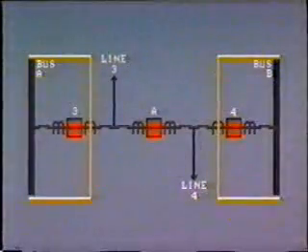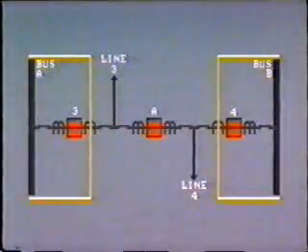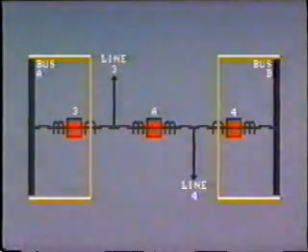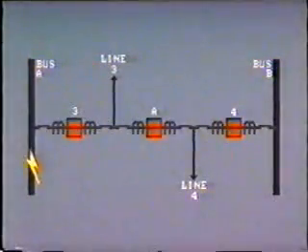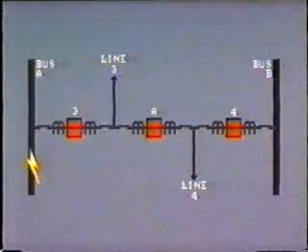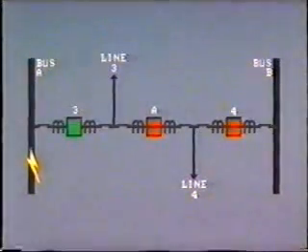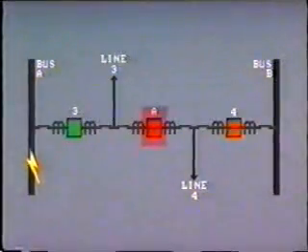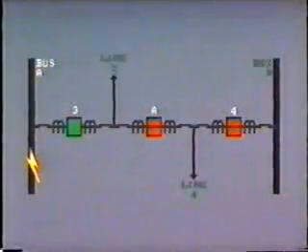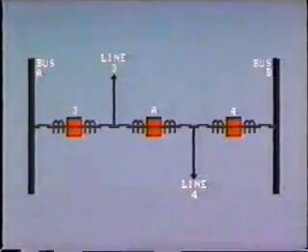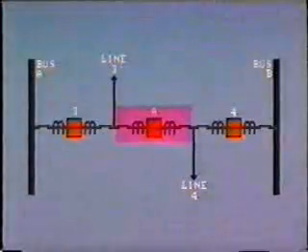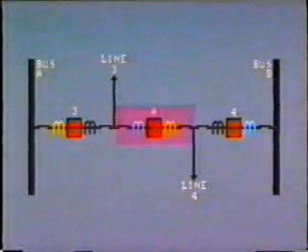Separate differential bus protection is provided for bus A and bus B. If a fault occurs on bus A, all A-side breakers will open, and since the shared breakers are normally closed, all lines are connected to bus B. The mid-bus sections are protected by the line protection.